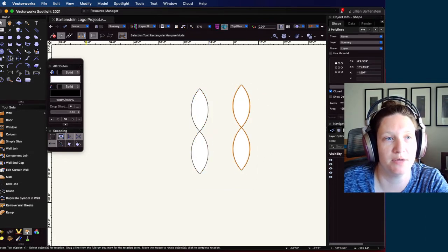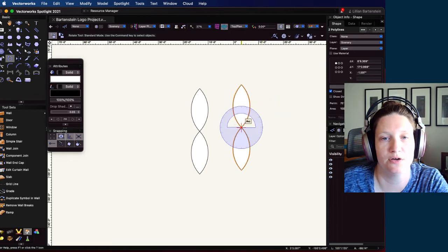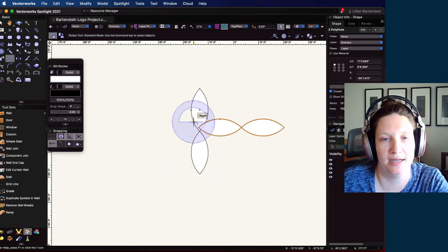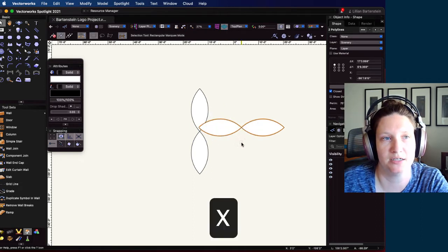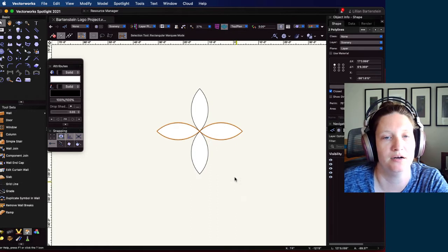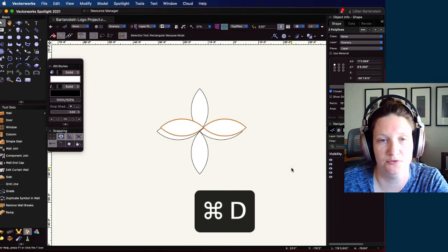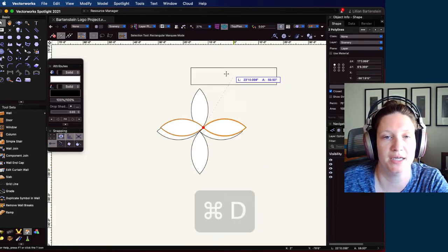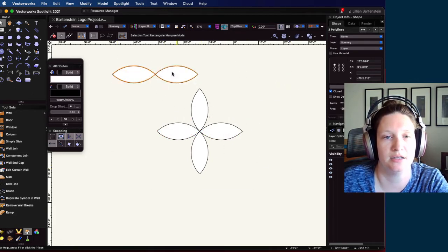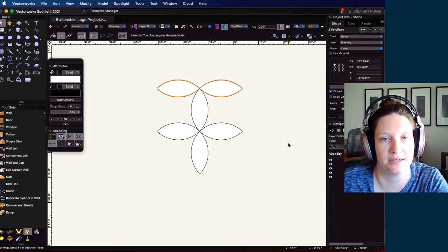Then I'm going to go pick up my Rotate tool, and if we remember right, rotate, you got to set a pivot point and then a handle, and that'll let me snap to horizontal. See how that's horizontal now? And then I can go hit my X key to get back to my pointer tool, pick it up from that intersection, and plop it in there, okay? I'm going to duplicate this again and set it up above. Duplicate. Again, I'm picking it up from the crosshairs, not clicking on any other things, so I'm just picking up those 2 that got duplicated and remained selected.